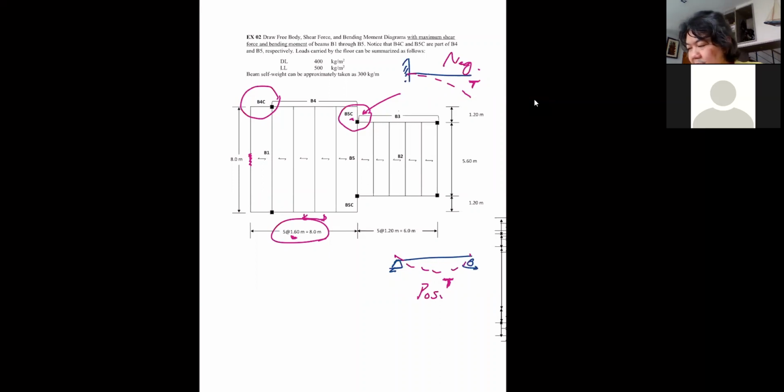So by giving it an extra name like C, when you check your drawings, you would know that the more reinforcement should be on top. If the draftsman makes a mistake of turning it upside down, you would know right away that it should not be right.